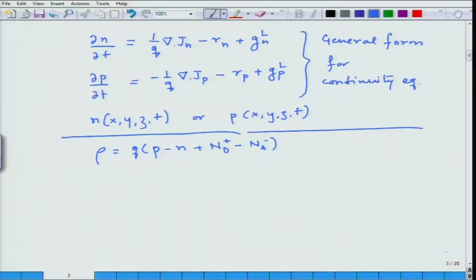If we know the charge density in the semiconductor, the next equation that we need to know is Poisson's equation, which is a differential form of Gauss's equation, which says the gradient of the field is given by charge divided by the dielectric constant, where the dielectric constant in a material is the relative dielectric constant times the electric permittivity of the vacuum. In addition to that, we have learnt during drift that current due to electrons is current due to electrons due to drift.